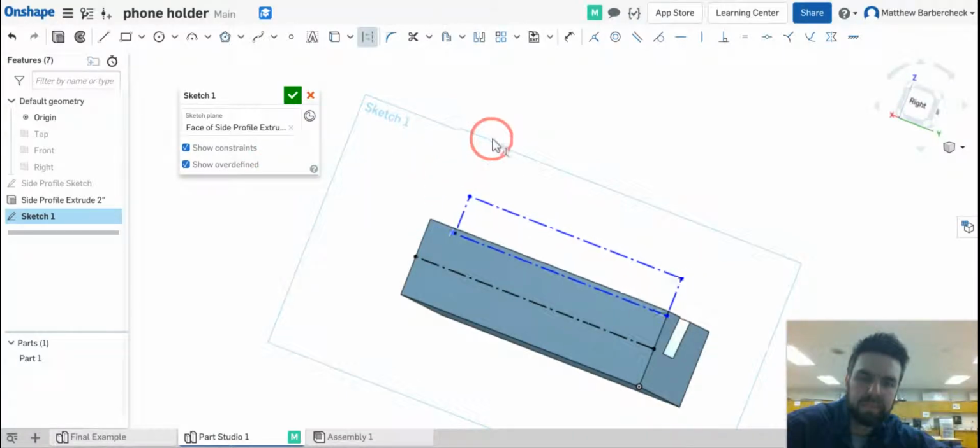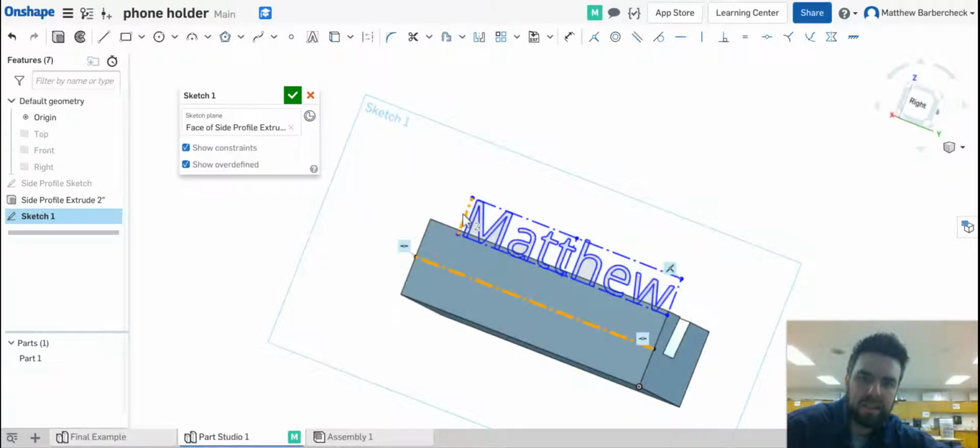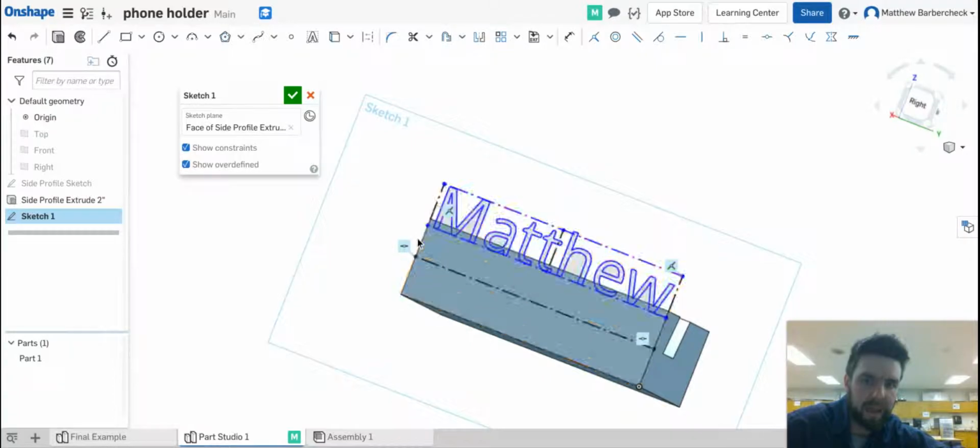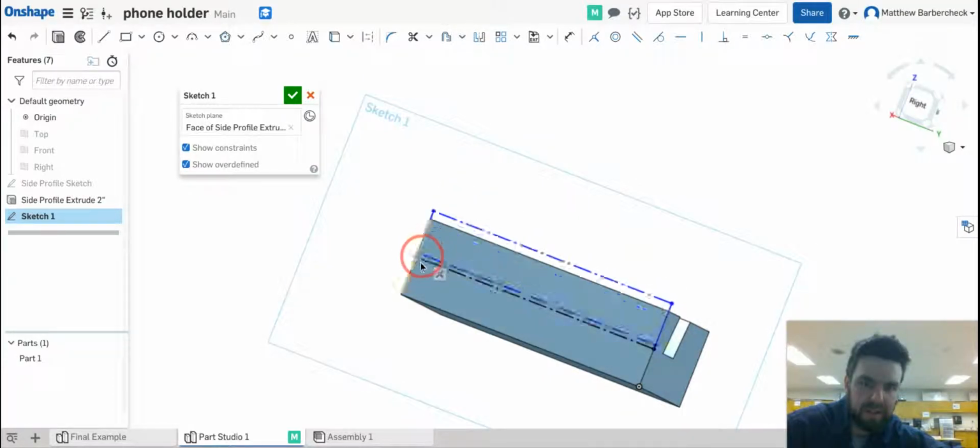Ooh boy. And I'm going to make this line and this line vertical. Oopsies, not vertical. We're going to make it coincident. That way, the end of this line always has to be on the end of this line. All right, see that? So now we're good.